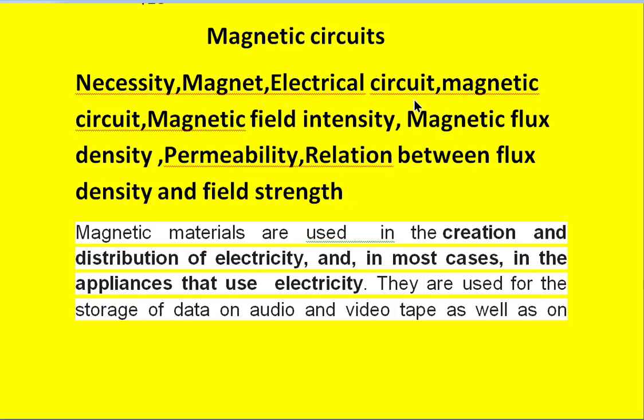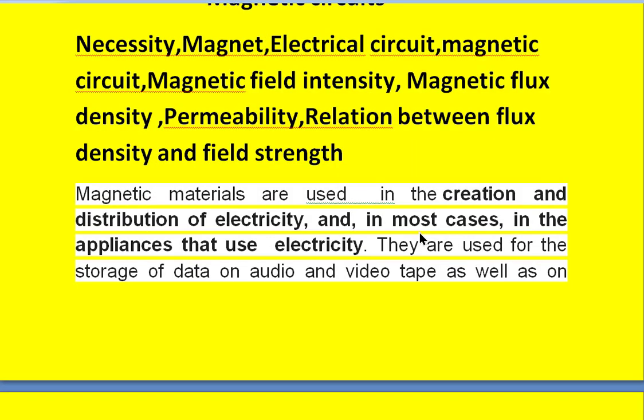And here it can be drawn that the electrical circuit is a closed circuit and there is no magnetic coupling there, whereas in case of a magnetic circuit, there is no electrical connection between one coil and the other coil, but there is a magnetic coupling between the two coils, and each coil will produce a flux that will link with the other coil due to the magnetic material associated with the two coils.